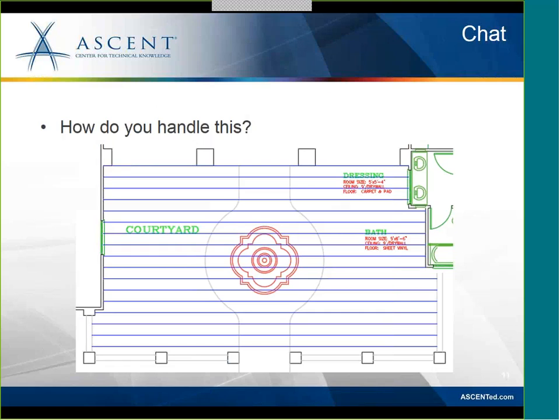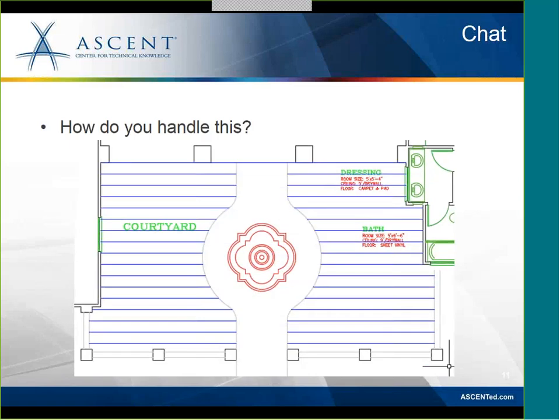So this is actually something, when I worked for Reevely Engineering, I did a lot of structural detailing for them, and we would have all these beams or floor joists or different things that would span the whole area. And if we had a rounded wall or something where I wanted to just trim them off, then I'd have to go and click each one individually until they came out with, of course, the fence command and being able to trim a lot of things at once. Basically, I could take that using the fence command.